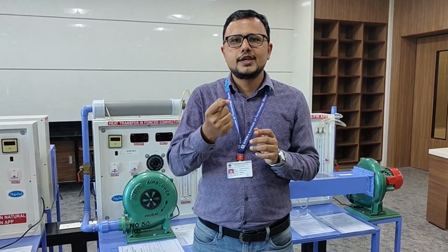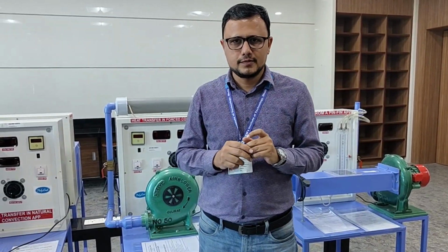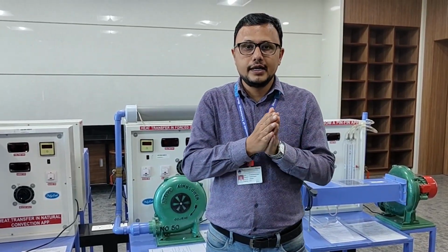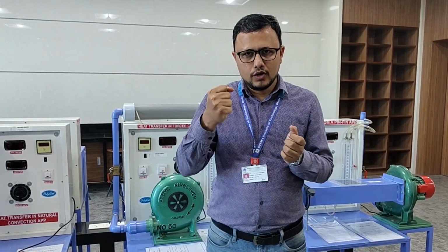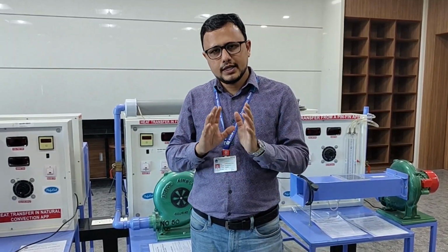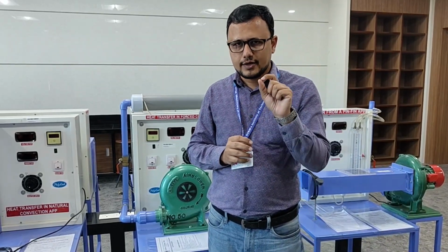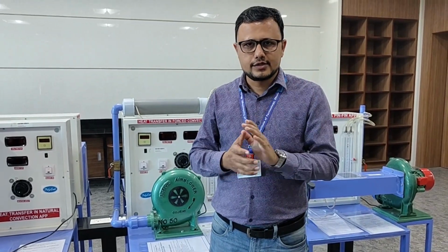If you go to the industry, in a boiler, when you are circulating water through the tubes, then it is done with the help of external mechanical force which is given through the pumps. And that's why that kind of convection will be forced convection. If you go to the refrigeration industry, let us say you are cooling a refrigerant in a condenser, you are circulating it through all the condenser tubes with the help of pumping or through the compression. Then it will be termed as forced convection. So there are tremendous applications of this. The main purpose of the forced convection mode is to increase the heat transfer rate, because heat transfer coefficient is more in forced convection than heat transfer coefficient in natural convection.